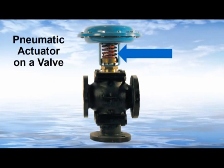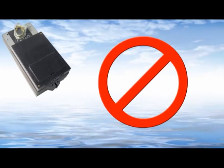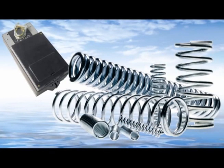When electric actuators began replacing pneumatics, however, they had no inherent fail-safe return. To remedy that, concepts from the old pneumatic spring technology were used to make spring return fail-safe electric actuators. As an electric actuator drove a load, it also tensioned a mechanical spring. To maintain position, power had to be continuously supplied. When the electrical power failed, the spring would return the actuator to its home position.